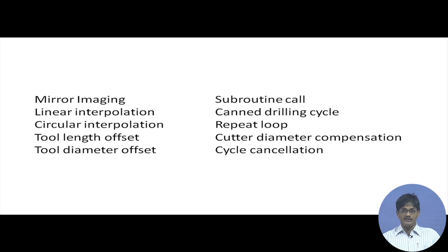The machine only knows dimensions up to the spindle nose and the machine table. Beyond that, if something is loaded on the spindle or placed on the table, the machine is completely oblivious about those dimensions. So, we have to declare to the machine in some manner the length of the tool protruding from the spindle and the job height above the table surface.